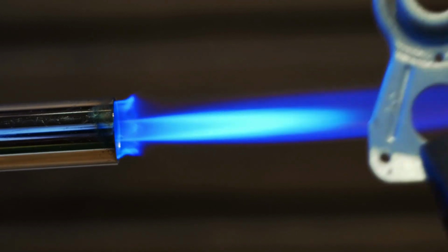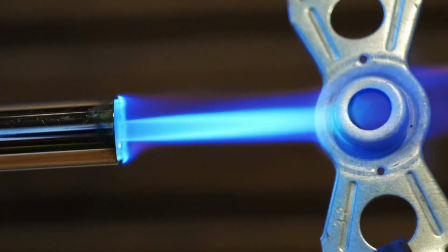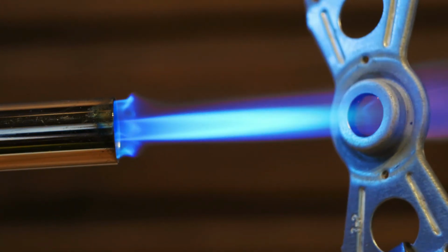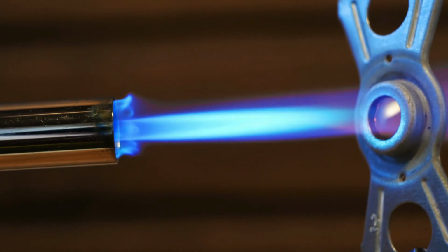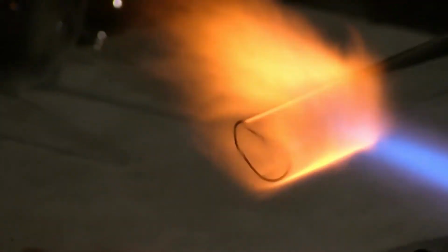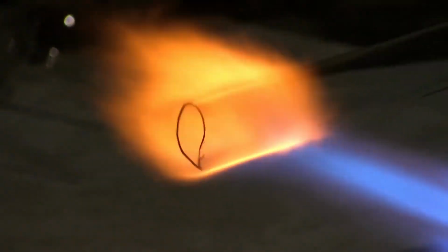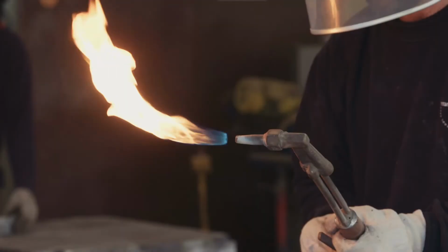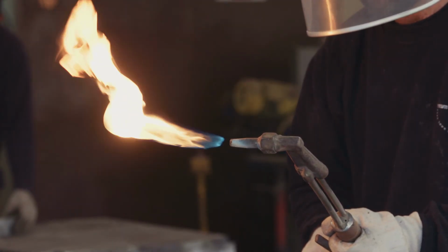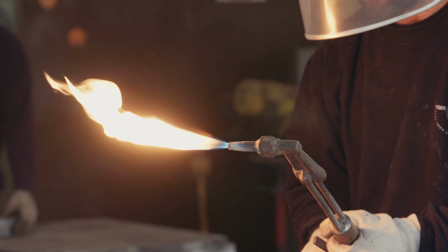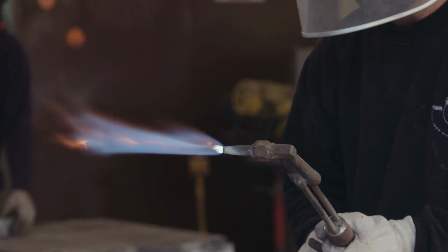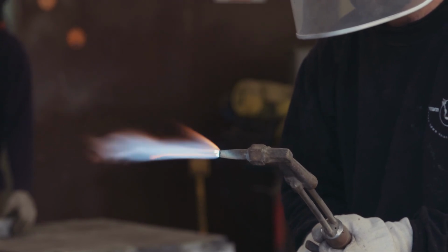When a welder uses an oxidizing flame on steel, the molten metal gets burned and starts to foam and form sparks. This is an indication that the oxygen reacts with steel. It depends on case to case, and the welder has to decide the distance between the flame and metal by looking at the response of the molten metal because of the flame. Therefore, some pre-thinking must be done before using an oxidizing flame for your application. It shouldn't be used on a metal that gets oxidized easily. Such metals are magnesium and aluminum.